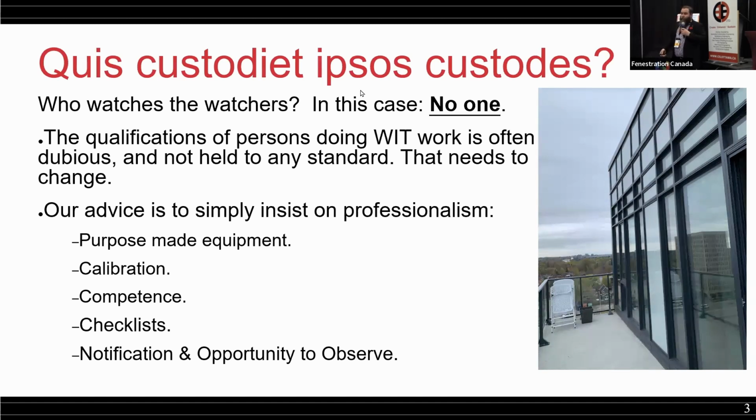That's not reasonable. The code is a minimum standard for a reason. The supplemental standard, either supplement to the Canadian standard, is there for a reason. If you're using the correct pressure on site, that's really what you should be held to. And I find it very frustrating to be up against engineers and architects trying to demand that the window meet its basically lab pressure. I don't think that that's all reasonable.